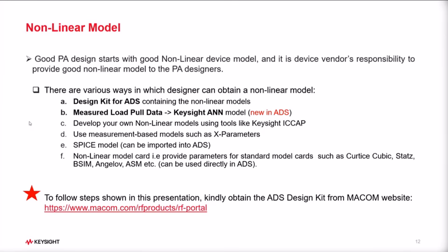If that device model is not accurate, you will never be able to do an accurate circuit design, right? So garbage in is equal to garbage out, simple relationship. And depending upon whichever is your device vendor or the foundry you are going to work with, in case you are designing IC, it is their responsibility to give you a good nonlinear model, which is validated against measurements, so that you can have a good nonlinear model to start your nonlinear design.